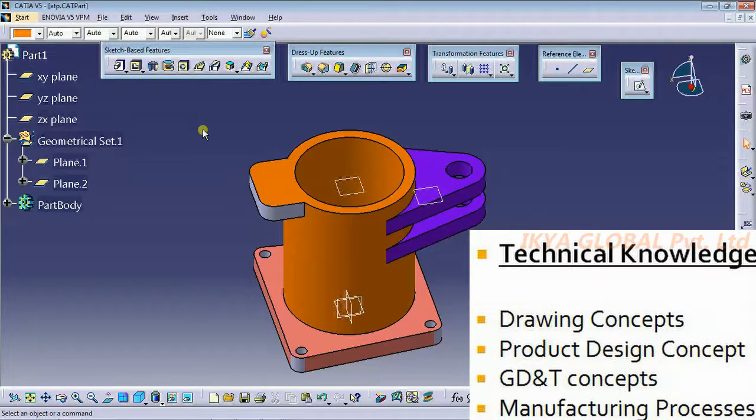Sheet metal or machining. No, this part is done by machining on milling machines. Why do we need to go for a milling machine? Why can't that particular part be manufactured by casting? The reason mainly is cost. It depends upon the part's per unit value and the manufacturing costs related to each other. If the component cost is more, you will get a higher per unit price, then you can go for some precision machining.